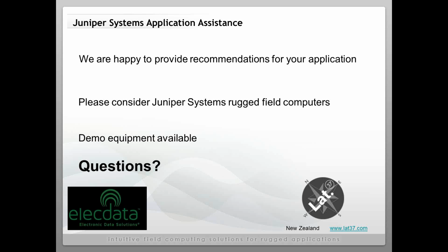Good, thanks Trevor. I think we'll just do one more and then try to answer the rest privately, if that's all right. Sure. We were asked if Steve could repeat the 3 different water probe brands that work with Hydro Plus. Oh, yeah, thank you. The 3 different brands of water quality probes that work with Hydro Plus are the YSI, what I refer to as the 6 series, so any of their multi-parameter probes that begins with the 6. The HydroLab 4A and 5 series will all work with it, and any of the In-Situ 9000 or 9500 series will work with it.